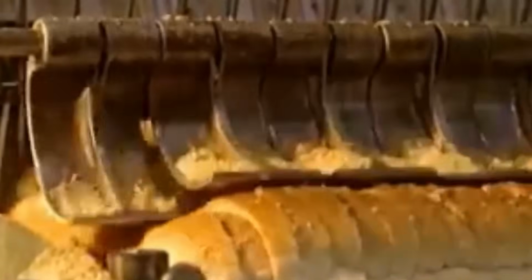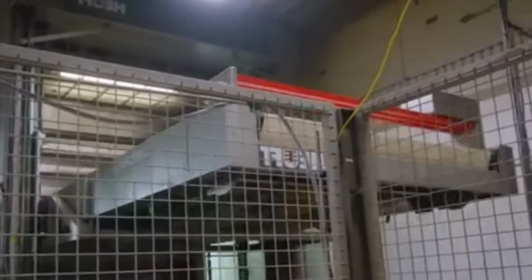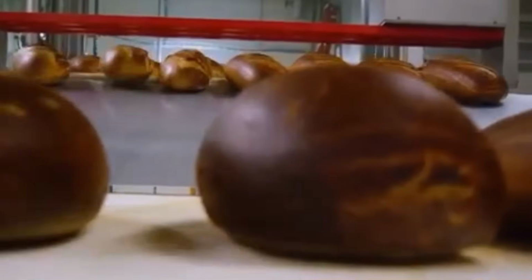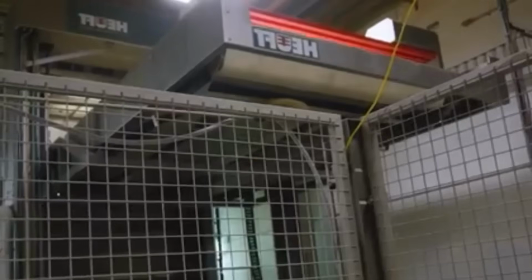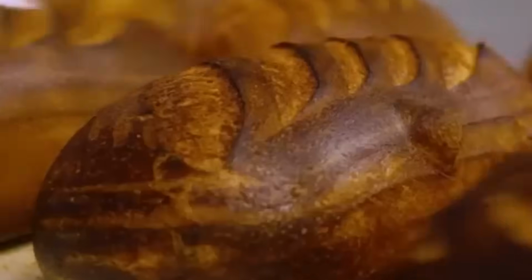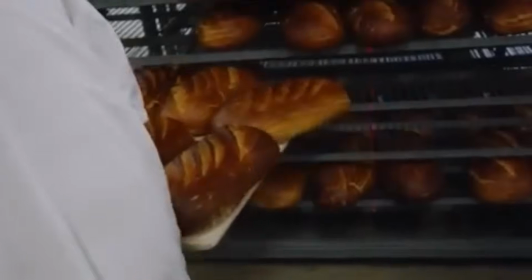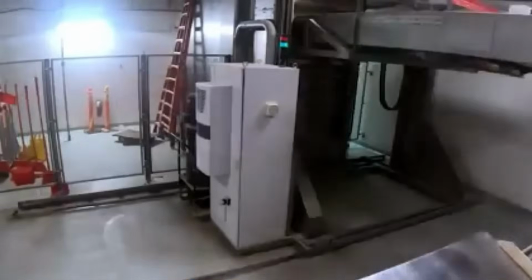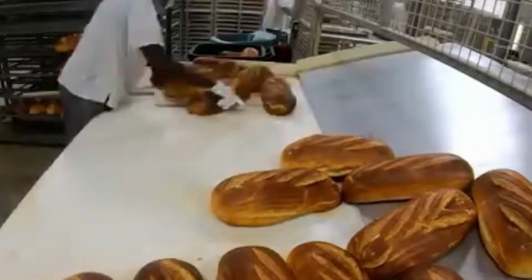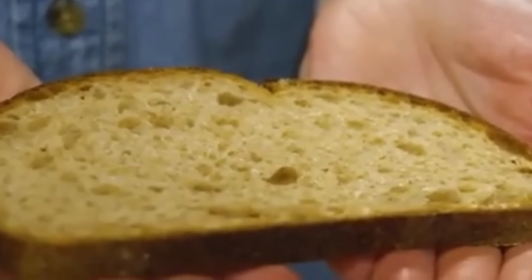The industrial oven is a continuous tunnel design, divided into multiple thermal zones with independent top and bottom heat controls. As the pans enter, steam injectors release a high-pressure burst across the loaf tops. This initial moisture keeps the crust soft in the early minutes, allowing for maximum oven spring as the bread expands rapidly under intense heat. The steam also sets the crust structure and eventually contributes to its color and gloss.